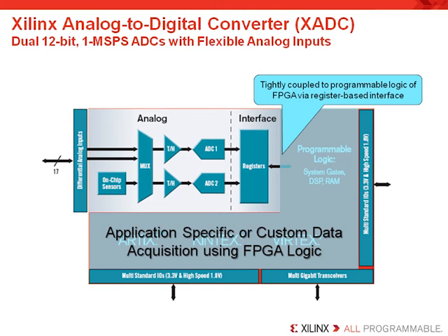After the analog signals have been accurately converted by the analog to digital converters, the logic resources in the FPGA, which include the DSP slices, block RAM, and logic functions, can be applied to correct or calibrate the transfer function of the sensor. By oversampling and using the signal processing capabilities of the FPGA, the resolution of the analog channel can be greatly enhanced.